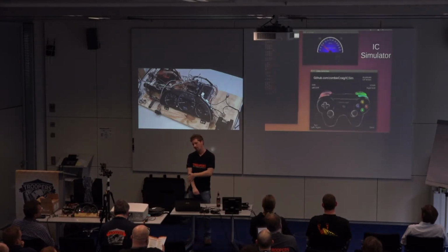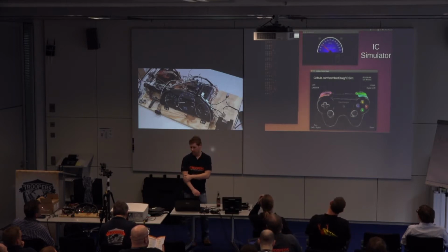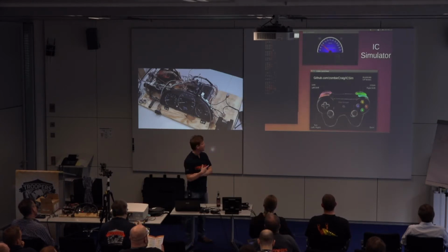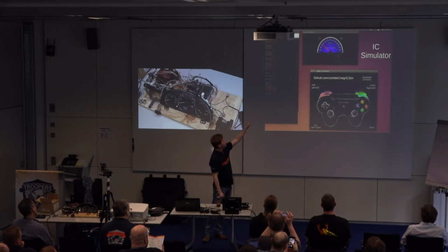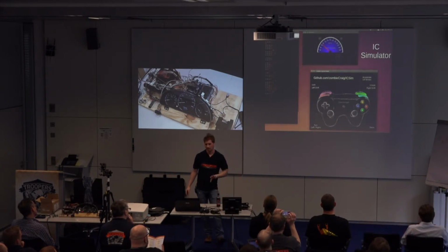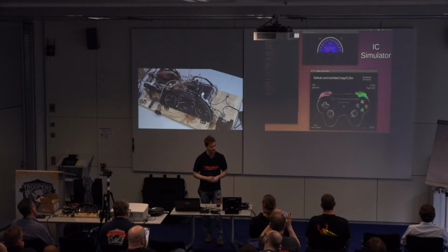The thing we're also going to use for live demos today is the IC simulator. This is a tool I wrote to simulate more or less what we have physically here. Your instrument cluster is at the top, and there's speed, turn signals, and door unlock. You can randomize the codes it uses every time you play this. It is meant to work as a game. You're going to reverse engineer the CAN packets to do those things, and you can give it a flag where the next time you play it, it's using a whole different set of codes. And you can change how difficult it is to locate them. So it's a good training tool.